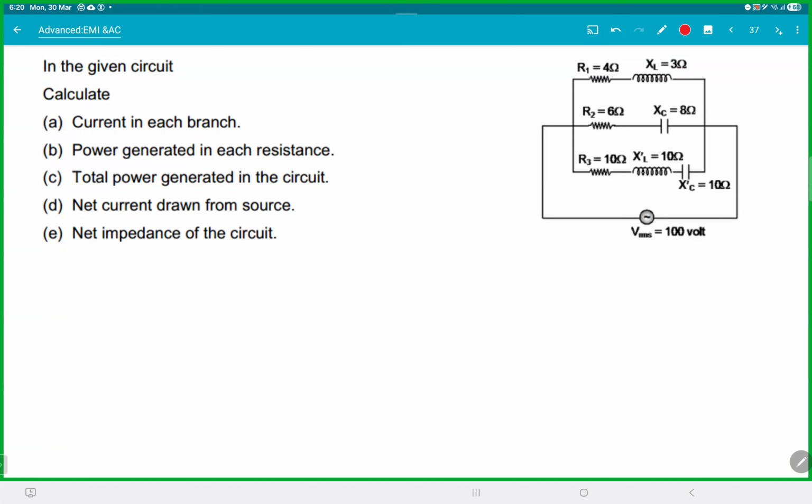Again, when they say something like current in each branch, they're not asking you for it as a function of time t. It's always RMS. Generally, you will figure that out from the options. Think about it. In an AC circuit, if they're giving you a constant value for current, that's not possible, isn't it? In an AC circuit, current or voltage should be changing with time, but the options are looking like solid numbers without any time dependence. They're asking about RMS. So keep that in mind. Unless they specify something specifically, if they just give you a constant value, it is an RMS value.